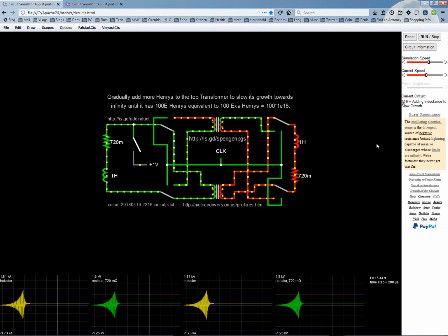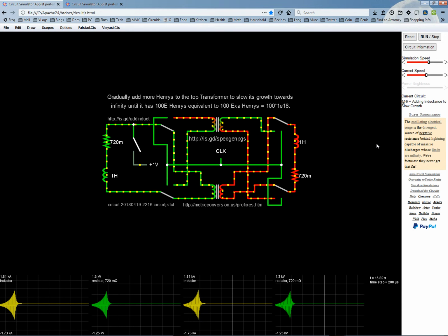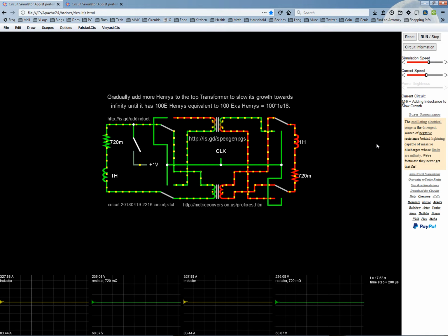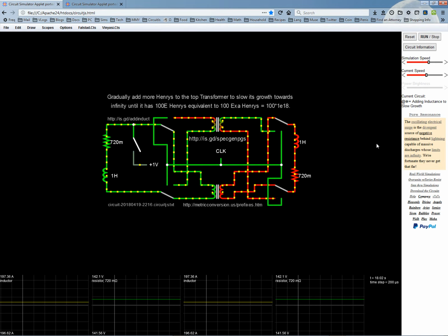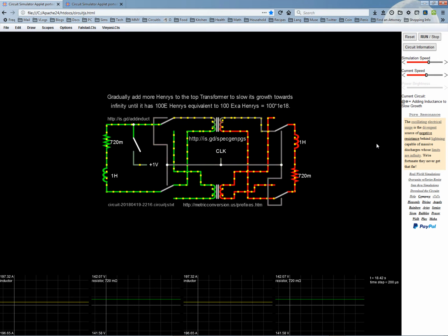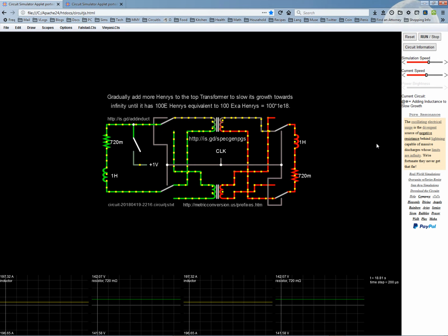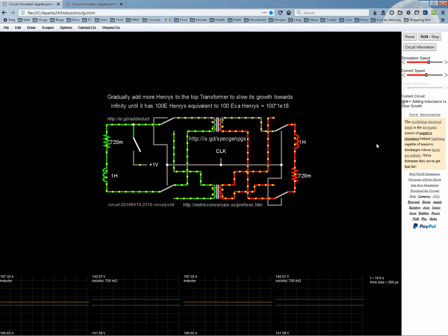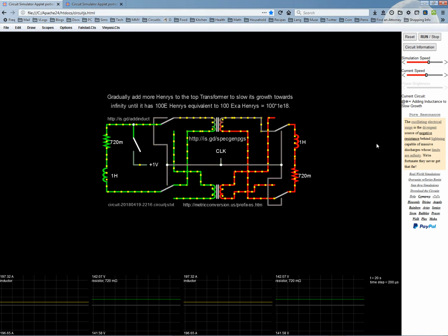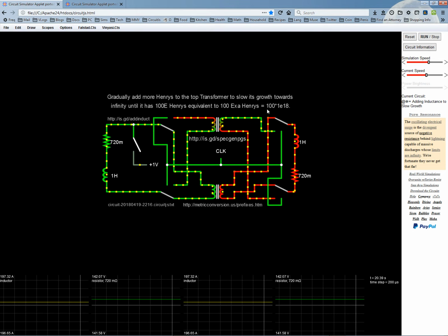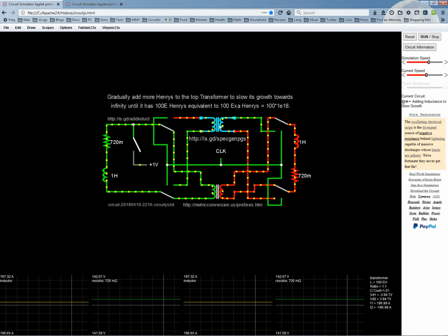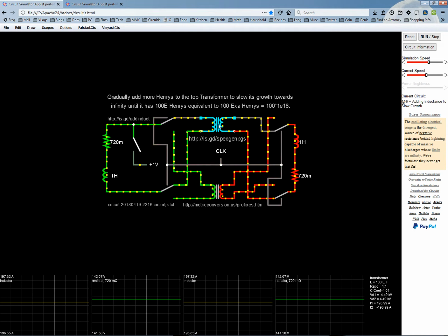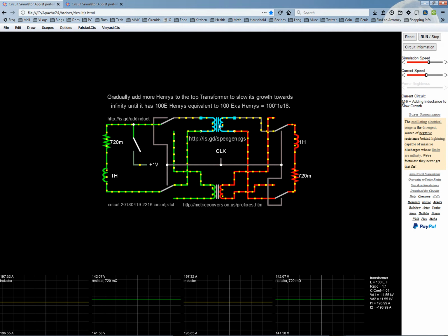It drops, but not down to 0. Drops down to its plateau of pretty close to what my pre-charged version is. 200 amps and 142 volts. How about that? So that's how you do it. You go up to kiloamps. So now this will run at a pretty constant rate because the amount of inductance is very high, but it's still 1.01 coupling coefficient.